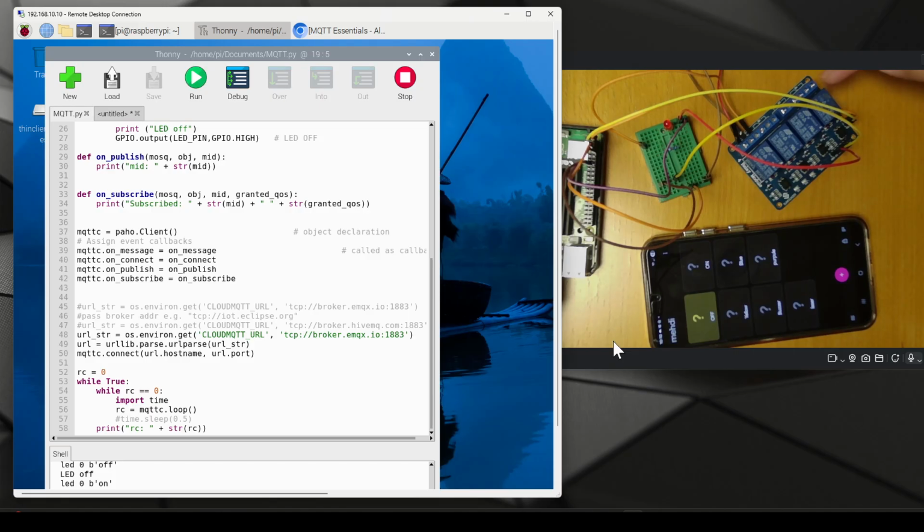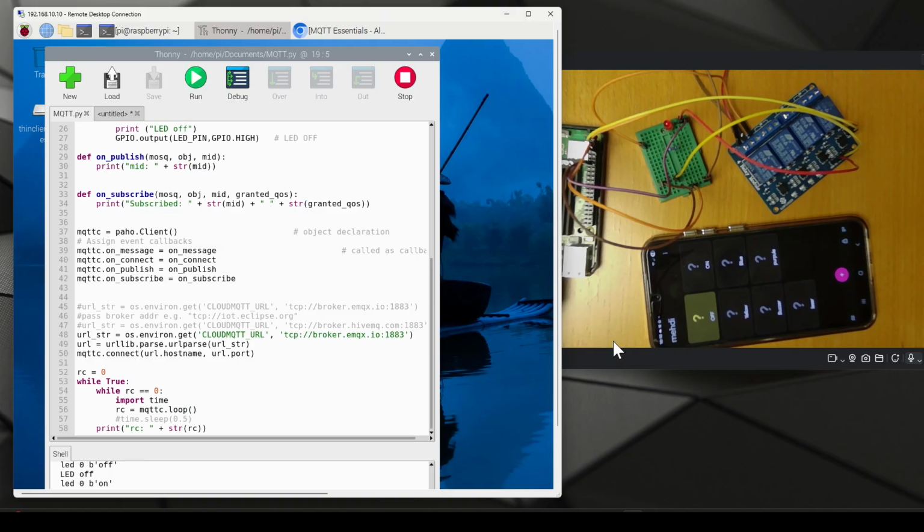And then maybe the question is why a relay board? Because with a relay board, through the output pins, you can control even 110 or 220 volt AC devices. These relays, as written on top of them, are good for 250 volt AC 10 amp, and also 10 amp at 30 volt DC.